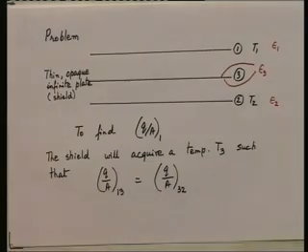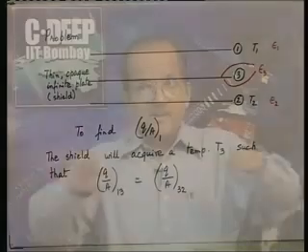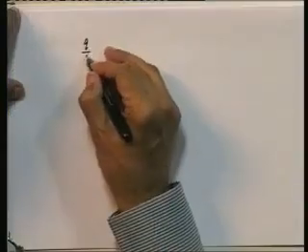Do you follow? That is what is going to happen in the steady state. If I put a shield in between, 3 will acquire a temperature T3 such that the net heat exchange between 1 and 3 is equal to the net radiant heat flux exchange between 3 and 2, right. Now, we can put down expressions for these quantities, we have just derived them. What is Q by A 1 to 3?